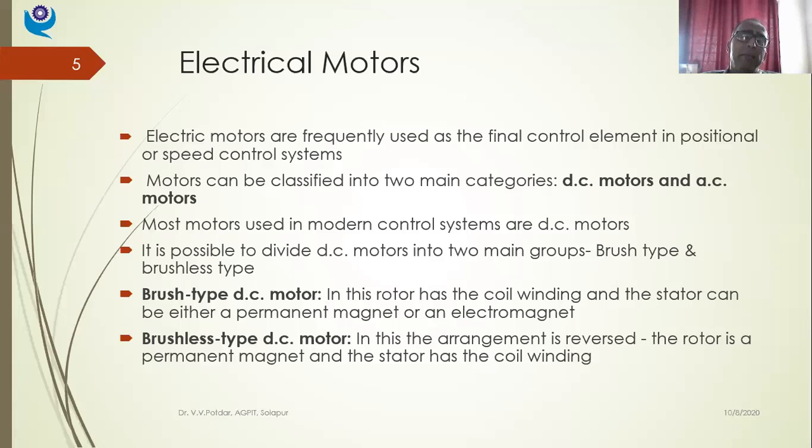So I have electrical servo mechanism. So what is the difference between electrical motor and electrical servo motor? In electrical motor, I'll be continuously getting the angular velocity or the RPM, a continuously rotating rotor. Whereas in electrical servo motor, I'll be just getting the positional change, not number of rotations. We'll be having angular positional change. So I'll be calling this angular position changing electrical system an electrical servo mechanism, whereas the DC motor or AC motor, electric motor, which is giving me continuous speed and torque, will be called the electrical motor.